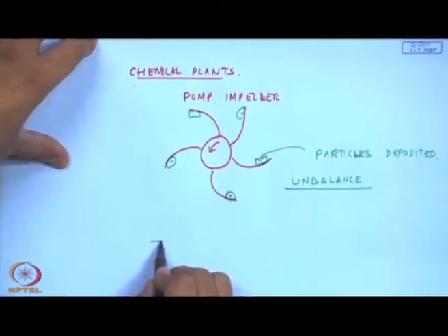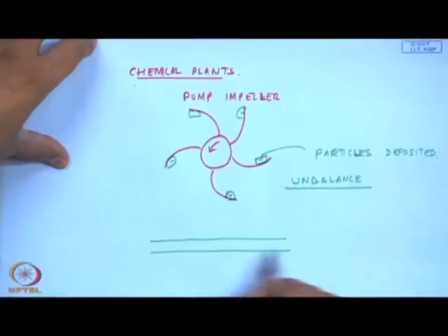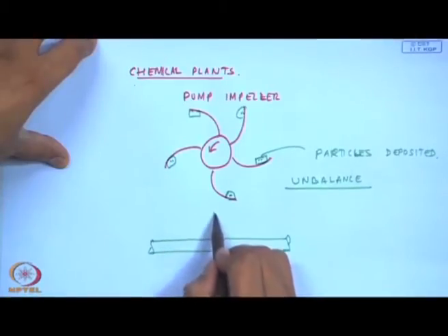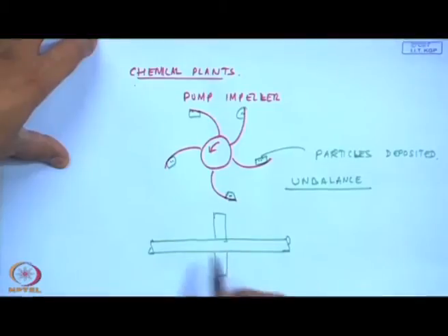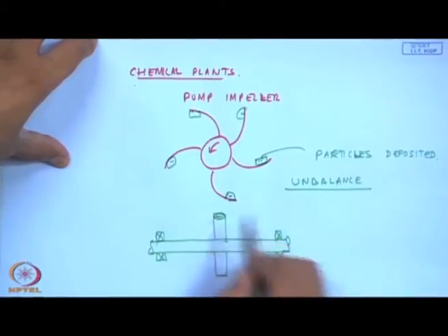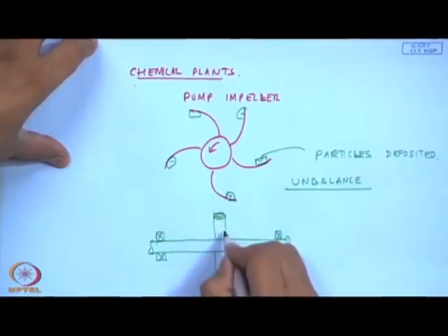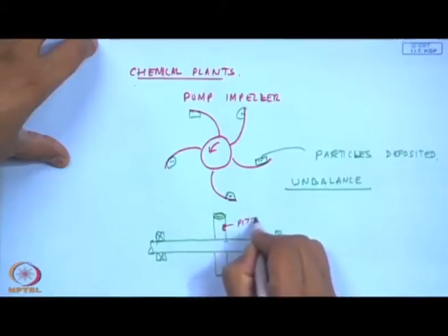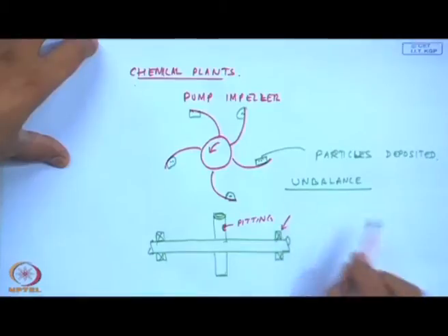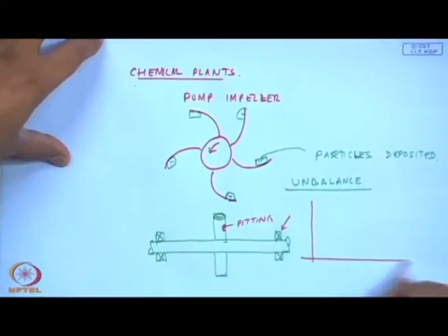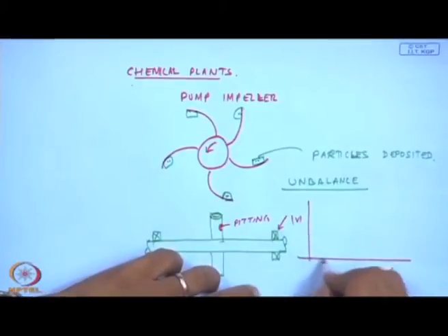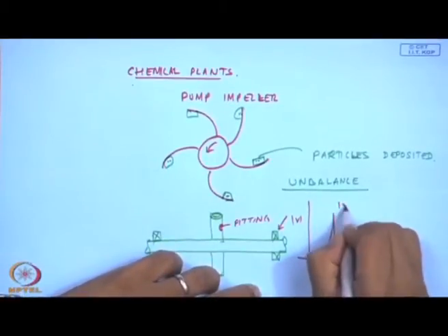So, if I have a shaft, and then either there can be unbalance and there can be pitting. So, all these will give rise to again the same problem which you see in the frequency in the vibration signal, a strong 1x component.